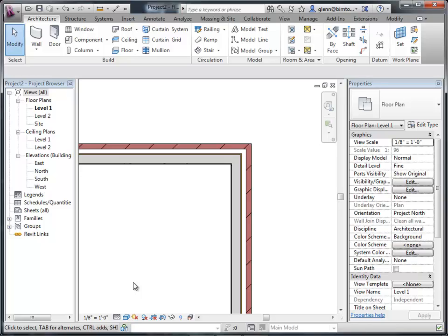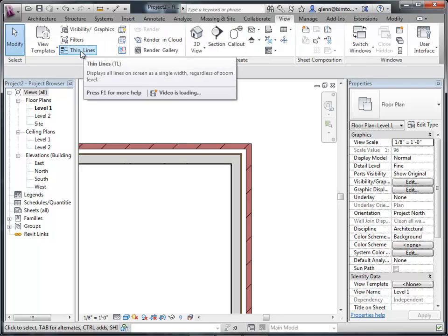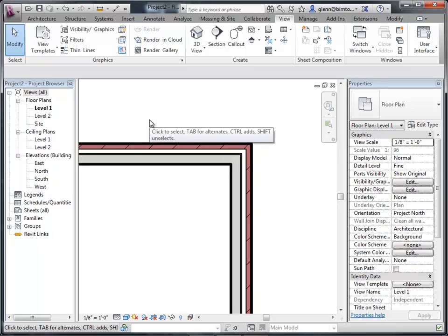Let me tell you about a visual display mode you can choose, and you can choose which way you prefer. By default, Revit shows with something turned on where it's showing you the actual thickness of the lines relative to the way they would be plotted. So the outside surfaces of the walls show up as thick lines. The interior surfaces show up as thinner lines. And if you actually plotted it out, that's the kind of line that we're going to get when it comes off the plotter or comes in the print.